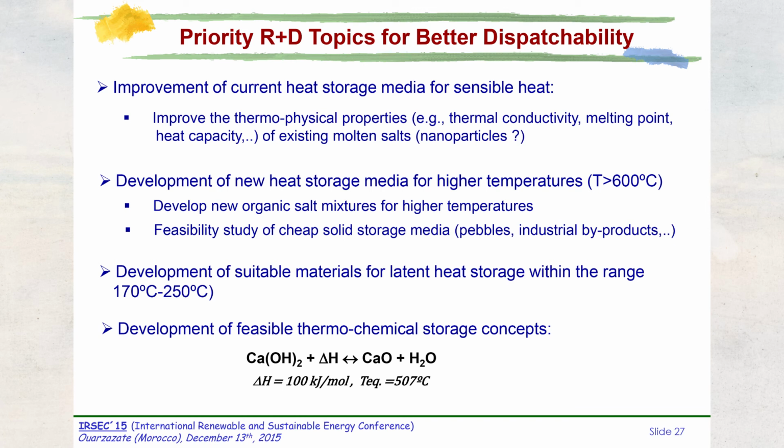A significant amount of water is evaporated in the cooling system. We evaporate approximately 3.5 liters of water per kilowatt hour of electricity. This is a rough number. It depends from one plant to another, but a rough number is 3.5 liters of water per kilowatt hour.